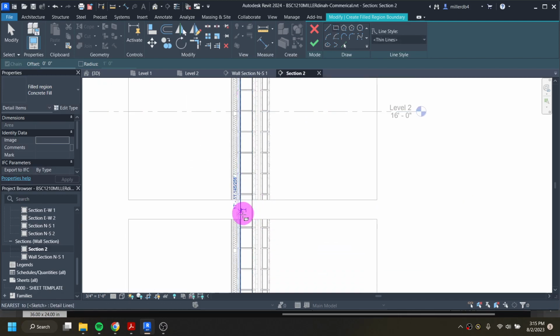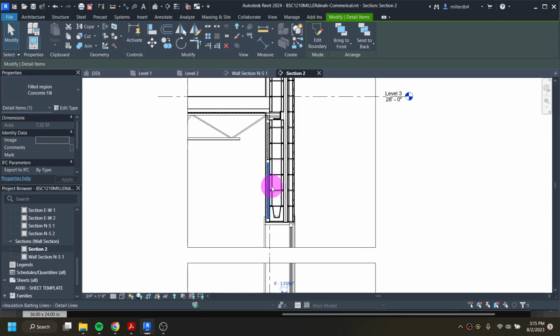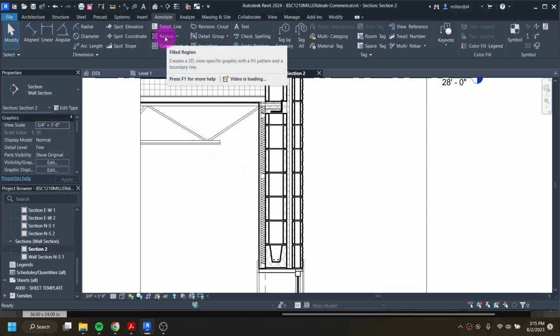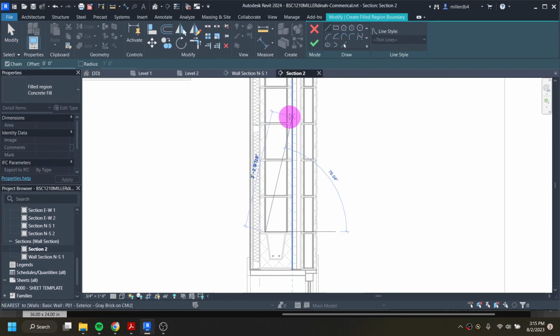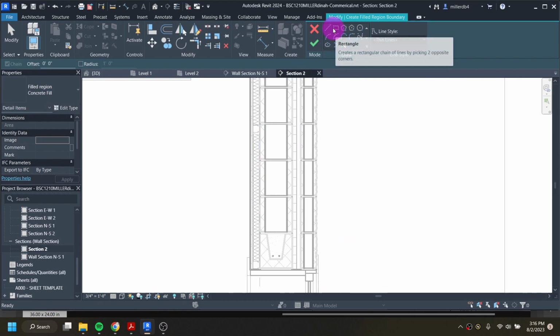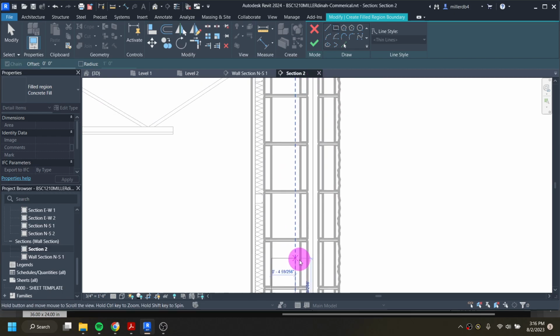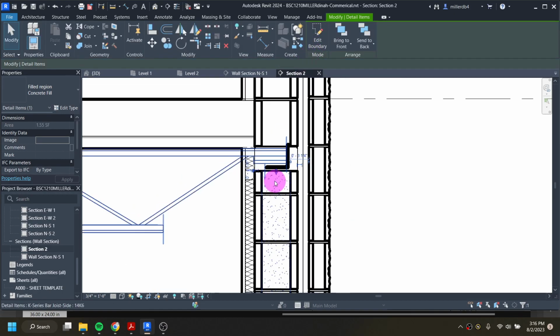Because this is not going to even be part of the drawing, it won't really matter when it comes to my actual drawing part. And then I'm also going to do filled regions up here. So I'll hit escape several times, region. I'm going to fill a region from here, which, whoops, I'm not in the rectangle tool. So I'm going to click on rectangle. Up to here and say, please create.